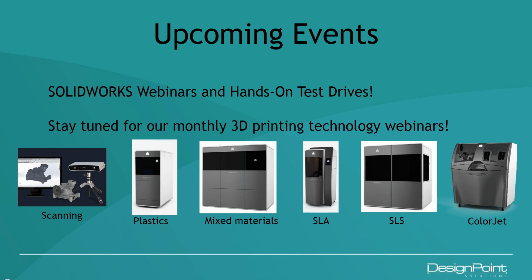So for example, they make a material that's ABS-like. They don't call it ABS because technically it's not ABS. It just has mechanical properties that come awfully close to ABS type properties. These are all acrylate-based resins that have UV curable binders in them. So I'm not sure I did a good job answering that question, but starting with the strength of the materials and the data sheets would be a good place.